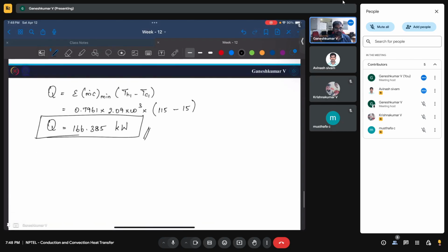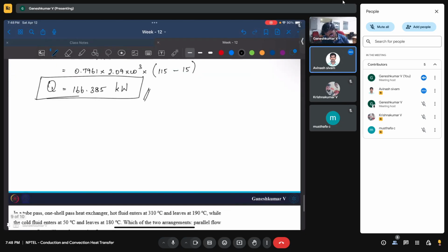This is your total actual heat transfer rate in your heat exchanger. So now that you know this, this heat transfer is going to change the temperature of both the hot fluid and the cold fluid. So you can write Q to be m dot h Ch times (Th1 minus Th2). Also you can write this to be m dot c Cc times (Tc2 minus Tc1). So from here you can get a Th2.